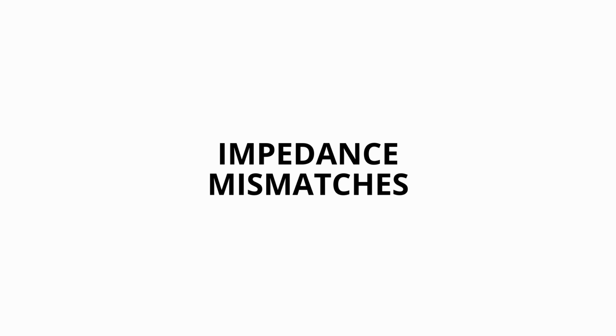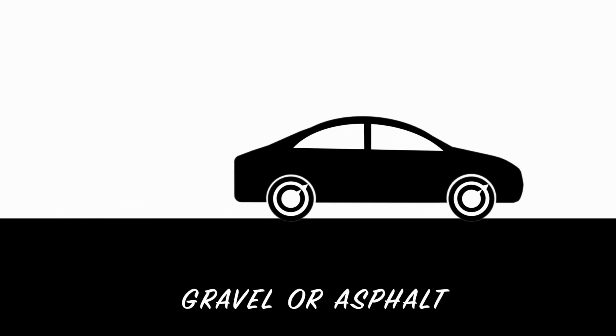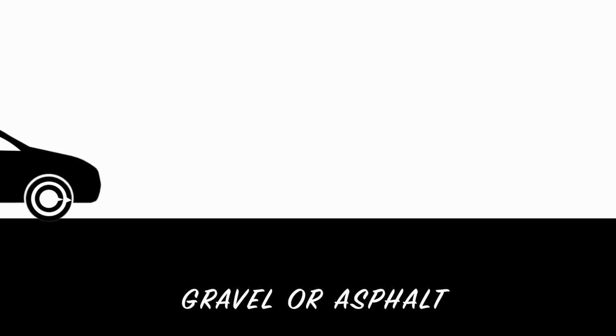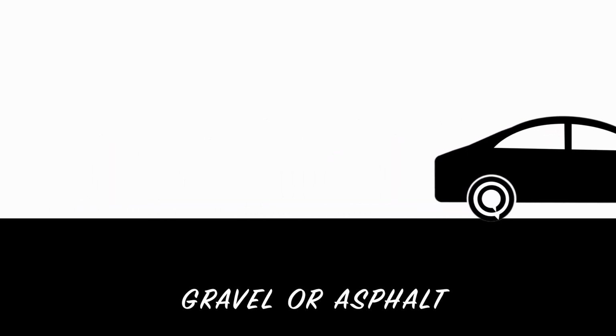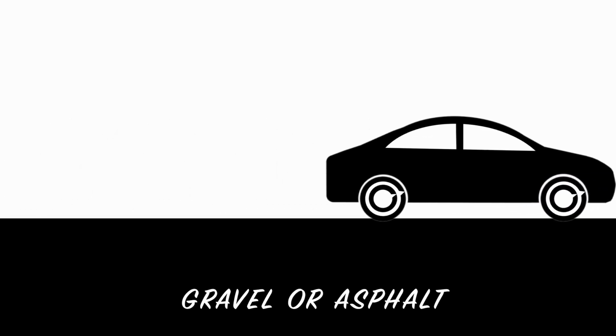Impedance mismatches. This may not be the most scientifically correct analogy, but here's a way to look at impedance. Let's think of your tube amp as a car and your speaker or speakers as the road your car is moving along. Your car is seeing just the right amount of resistance when it's moving on a straight and level gravel or asphalt road, as it was designed to do. Let's pretend that this is a perfect impedance match, like 8 ohms into 8 ohms or 16 ohms into 16 ohms. With tube amps, it is recommended that you always match the speaker output to that of the speaker.